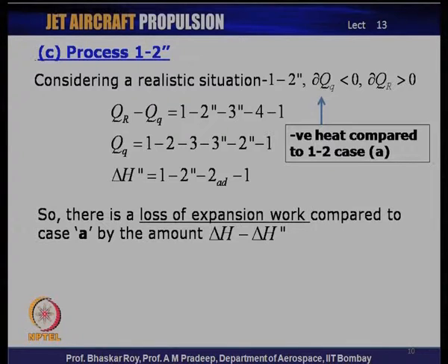So, when you are applying cooling for improving the life of a turbine, you are making a small sacrifice: the amount of work that would be available polytropically would now be slightly on the lower side. So, this is to be done in a knowledgeable manner, and this allows you to make a reasonable calculation and have a priori knowledge of how much you might be sacrificing in the process of applying cooling to the turbine blades.